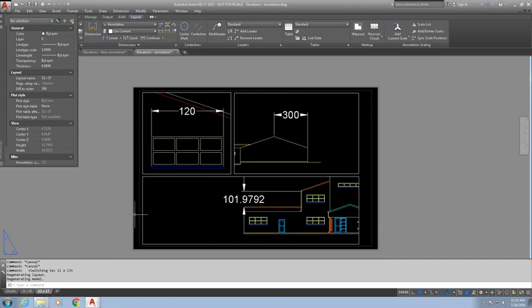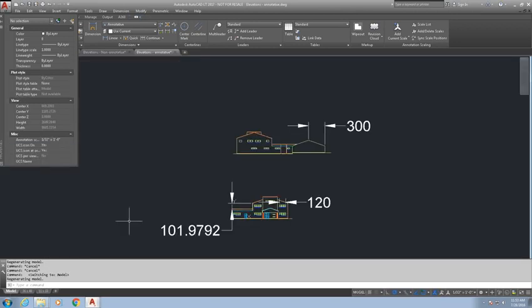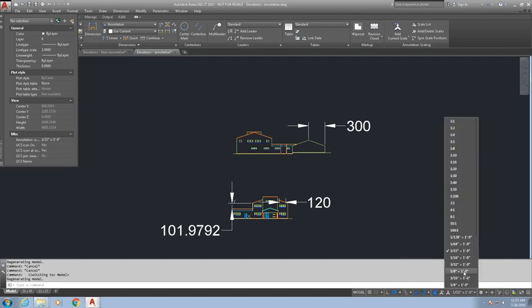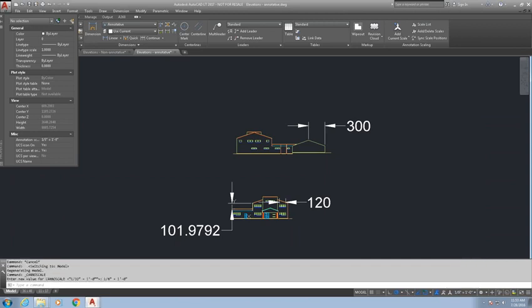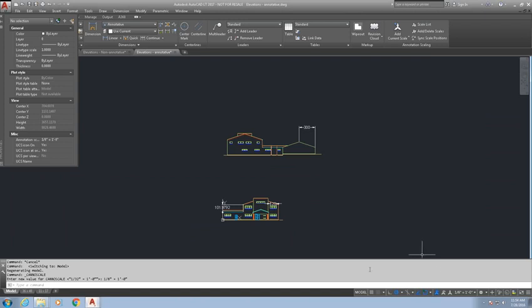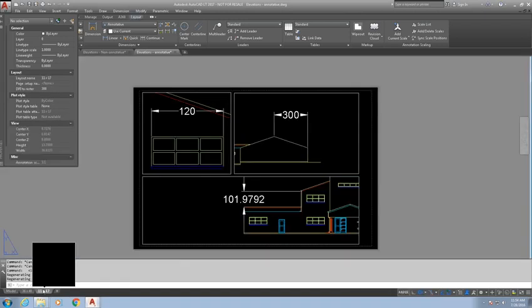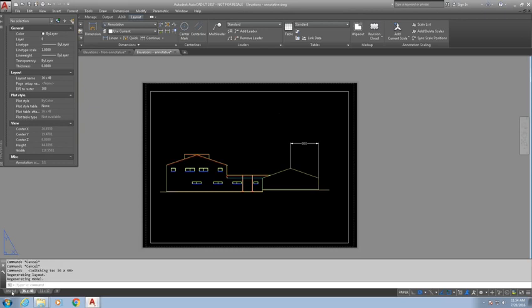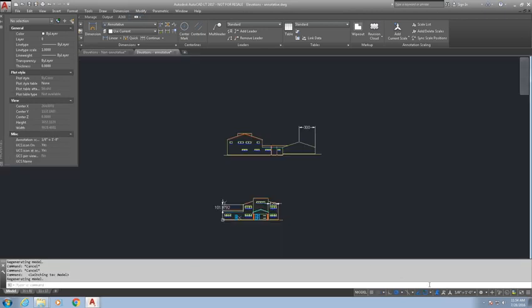Now, to accomplish this, you've got to be wary of a couple of things. When you are on your model and you go to draw dimensions or text or any other annotative object for that matter, there is this scale adjustment down here that adjusts your annotation scale, and I'll show you what that does. If we change it to 1/4 inch equals, or 1/8 inch equals a foot, for example, you see the size of the text differently. Now, if we go back to a layout though, it hasn't changed anything because I only changed the annotation scale on the model tab.